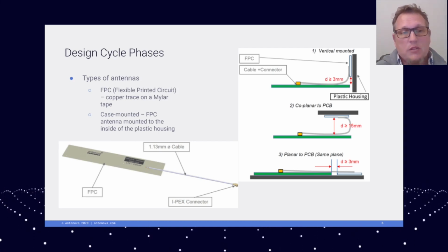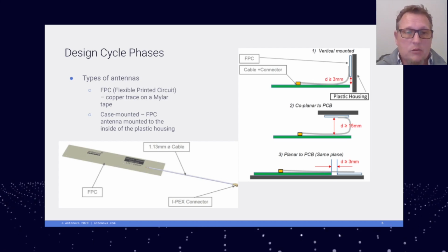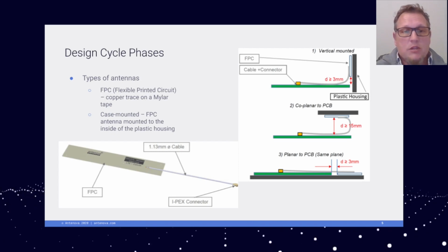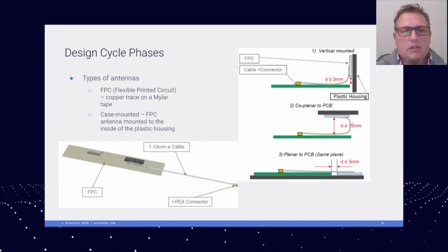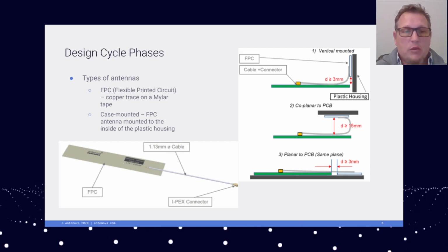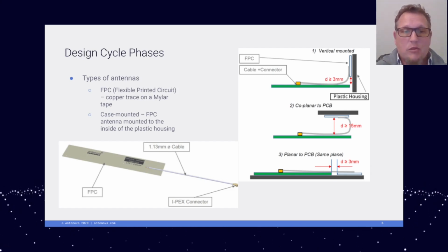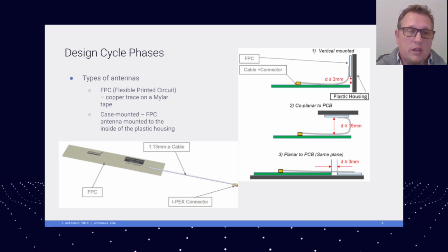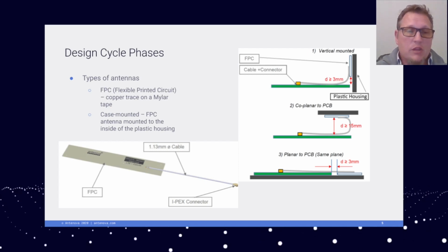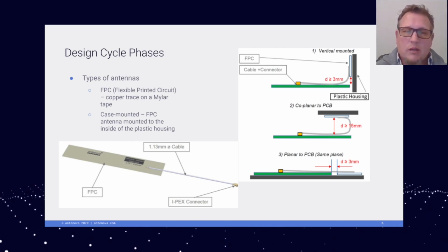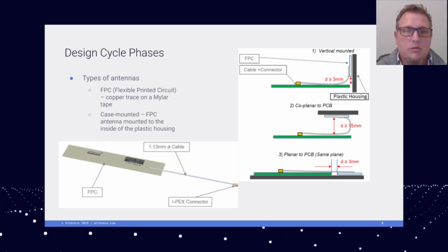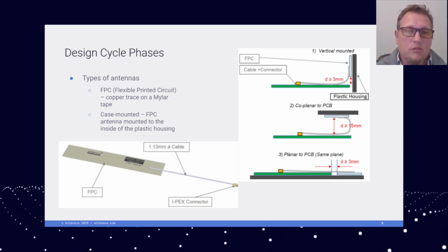And that noise feeding into your receiver front end will degrade your overall radio performance. These antennas also tend to be a little hands-on when you're manufacturing with them. In saying that, what I mean is that somebody has to stick it to either a carrier or the inside of your device. So that in itself takes time, and it also allows for some irrepeatability or some difficulties in repetitiously placing the antennas in your device.